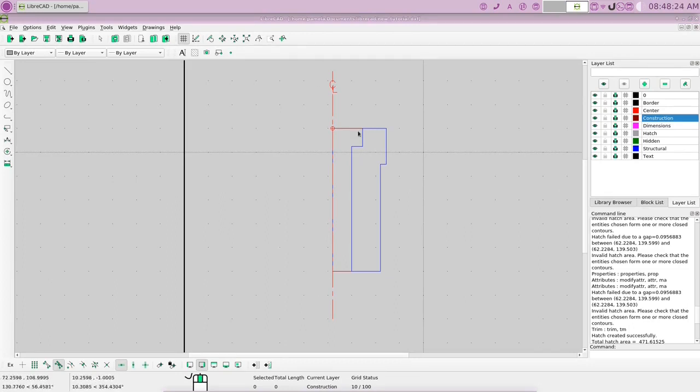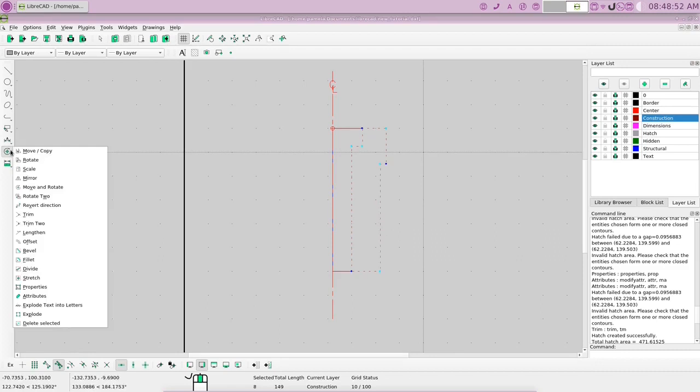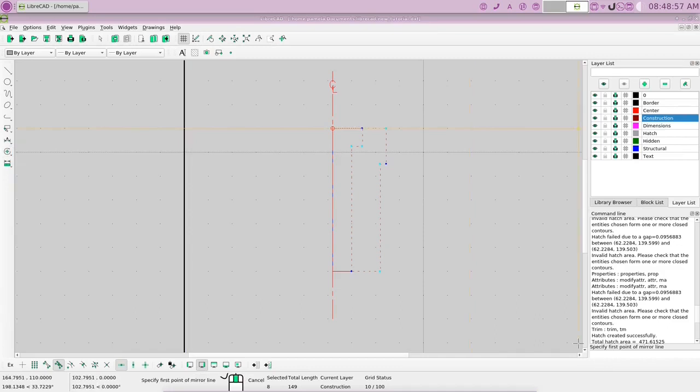However, this other side is not going to be the same view, but we can use some of the same lines. So we could actually draw the other side as we did this side, or we can do it an easier way, and that would be by selecting some of these lines that we're going to use, like that, and then from the modify, choose mirror. Okay, and if you look at the command line down here, it says specify first point of mirror.